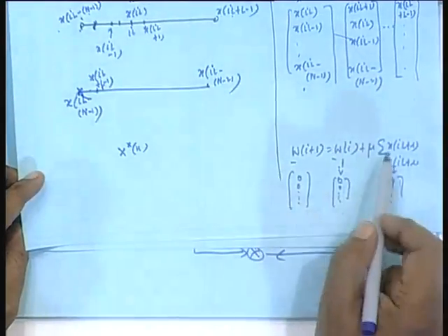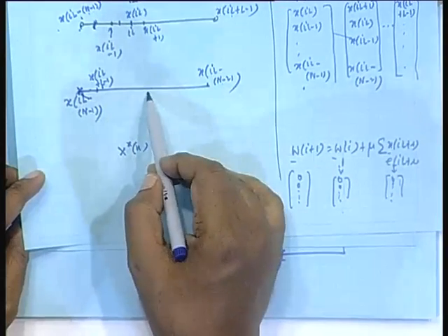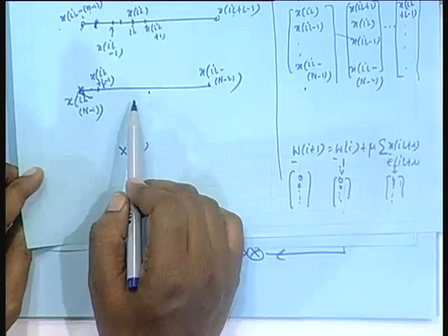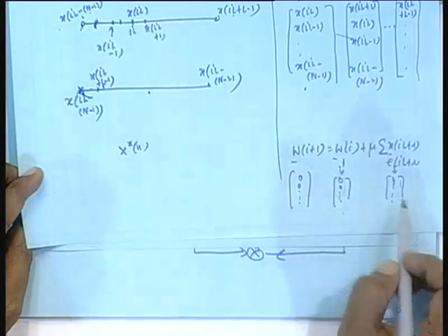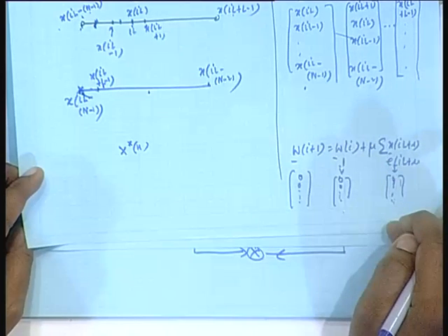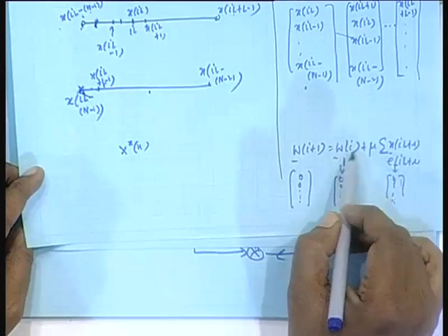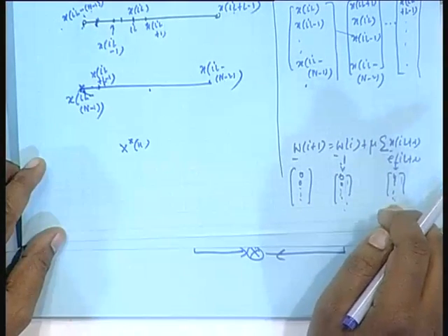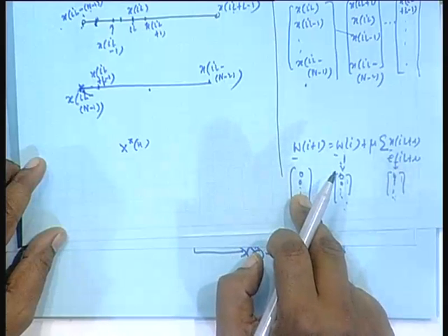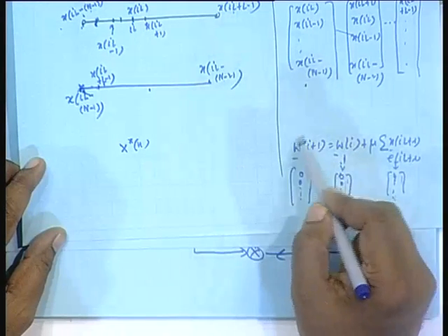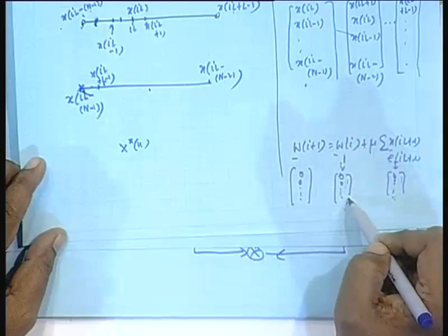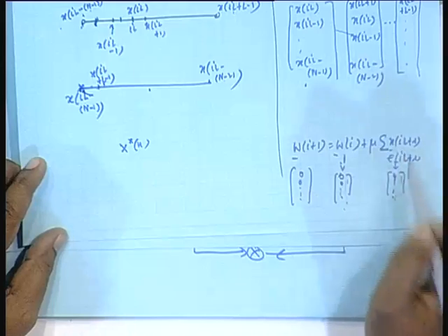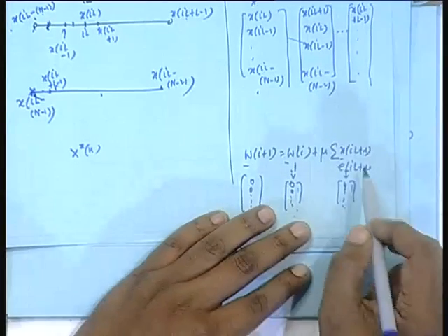So, in the weight update part, to carry this out, I told you that I will take circular convolution between this and this, but I need only the first n, remaining ones I do not need, but I put in zeros there. So, that this 0 vector comes below. And suppose in the previous block, the weights have been updated like that, the last L minus 1 guys are 0. So, if you do the update, this also will have 0, isn't it? Now, DFT of this is DFT of this plus DFT of this, isn't it? But DFT of this means what?